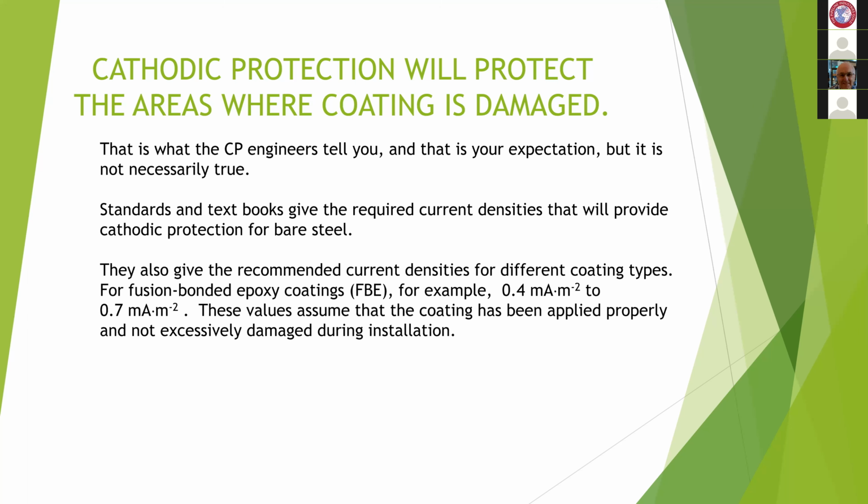So if you suddenly come across a pipe which has been handled very badly and the coating's been damaged and it's been thrown in the trench and there are obstructions in the way to stop the current getting there, these figures won't work, because the designer will not have allowed enough power or current for the cathodic protection to deliver that much. It's a bit like having too small a motor to drive a very, very big vehicle. It just won't work.